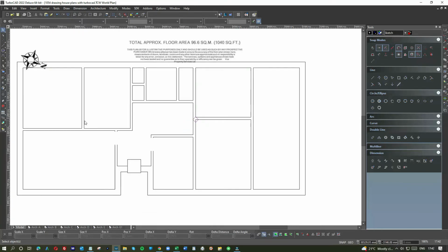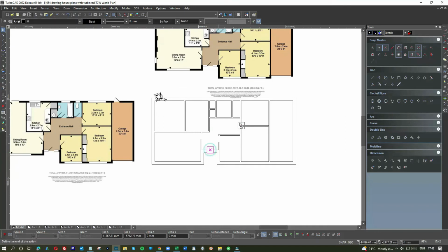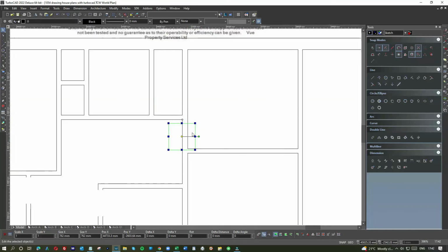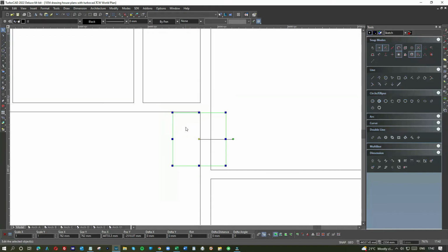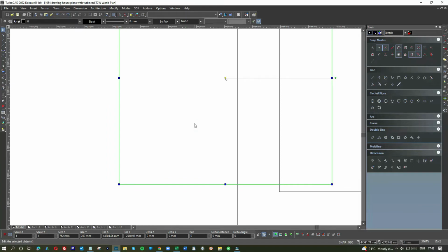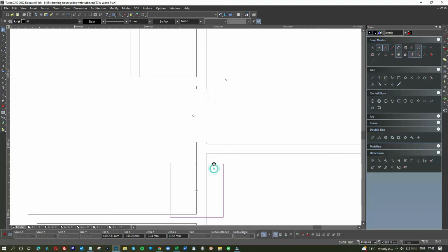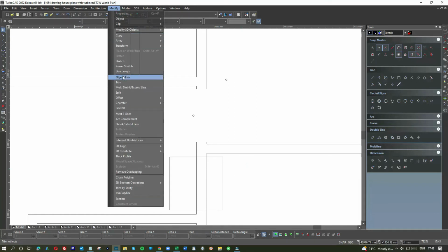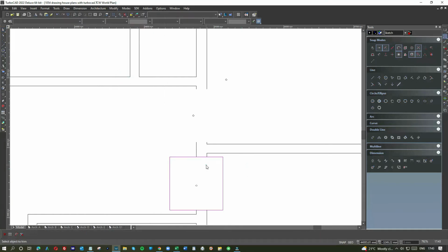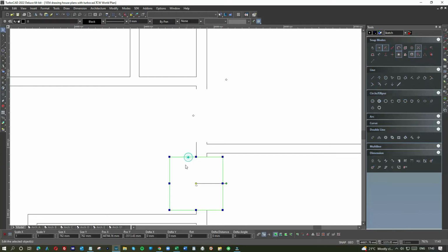Now, we need to get our doors in. Let's see if we've got the sizing. Yeah, always these bungalows, they're notorious for being narrow, meaning that you're cutting off architrave and so on and so forth. They skimp, they have thinner walls, and it depends on when it was built. They got worse through the 60s for a while. In the 60s, a bungalow, no insulation, the thinnest wood, the thinnest and slimmest walls.